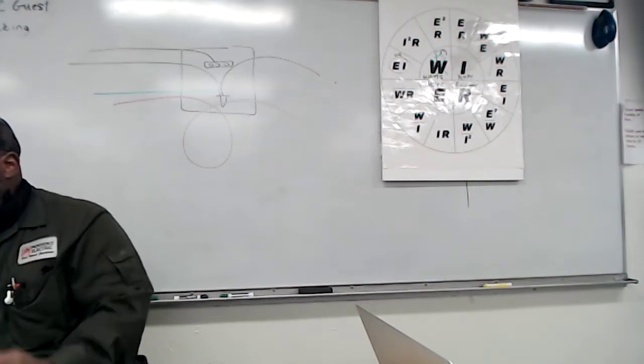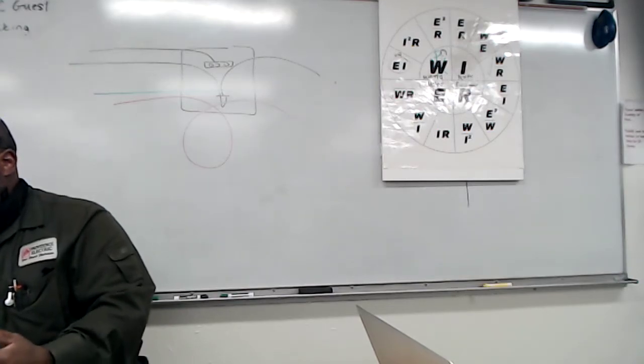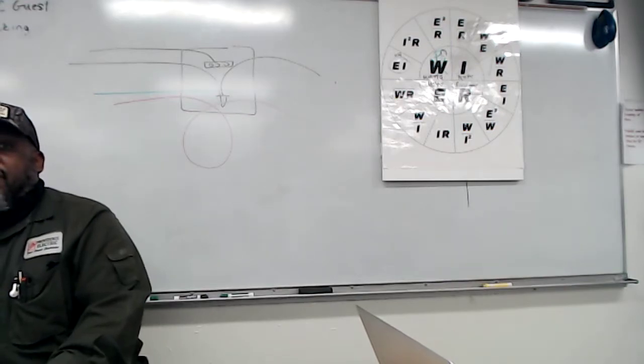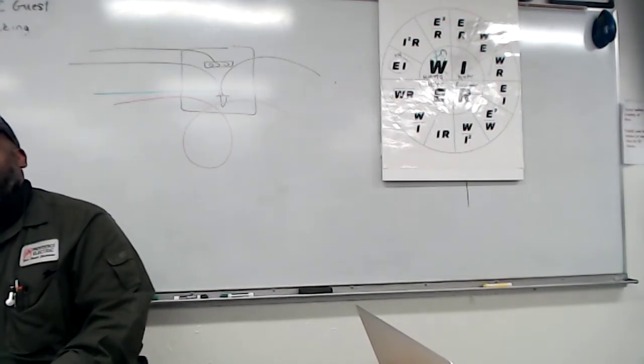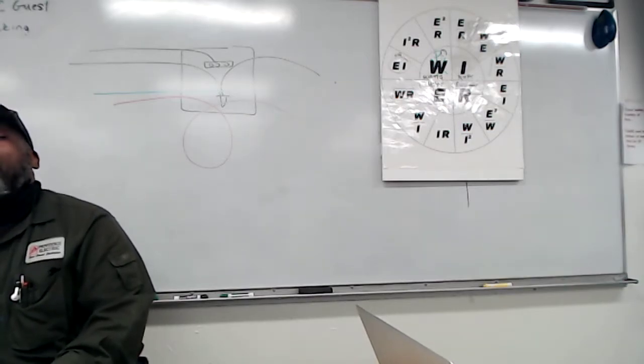4. Each yoke or strap containing one or more devices or equipment, a double allowance from Table 314.16(B) shall be made. So if it has a plug in there, that plug is on a yoke. The part of the plug that's grounded is called the yoke.